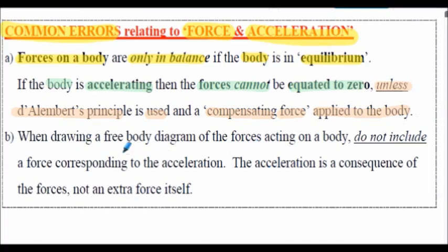Second point, when drawing a free body diagram of all the forces acting on a body, do not include a force corresponding to the acceleration. Acceleration is a consequence of the forces applied to the body. It is not a force in its own right.